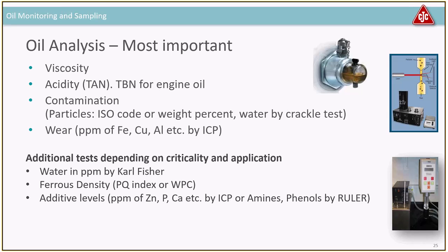And you're going to look at more details on the additive level, so zinc, phosphorus, calcium, and whatever you have. Or you may look at amines and phenols by RULER if you have turbine oil, for example.